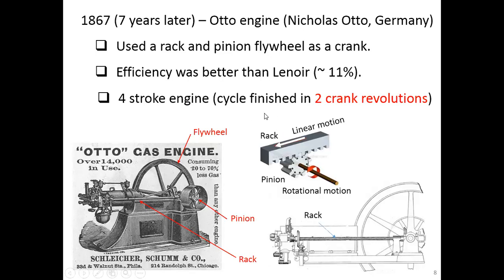That means the cycle has to finish in two crank revolutions, or the crank has to move 2 rounds in order to finish the cycle. But unfortunately, there is only one power stroke in 1 round. In the other round of revolution, no power comes out.